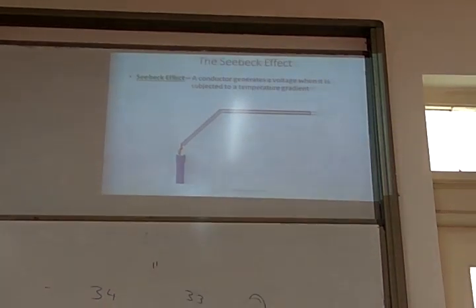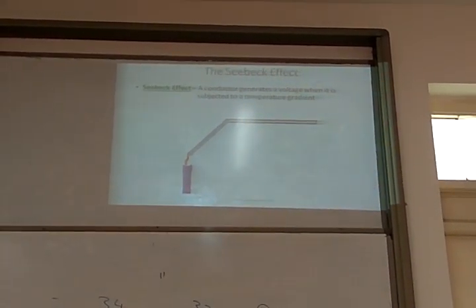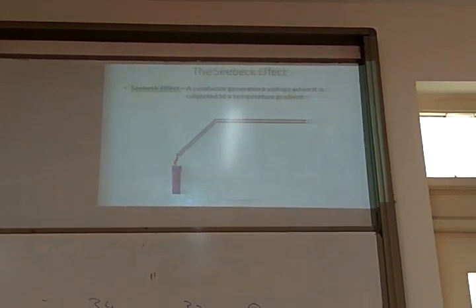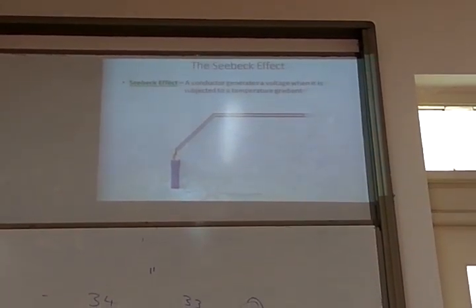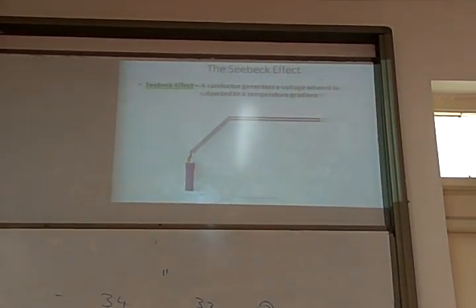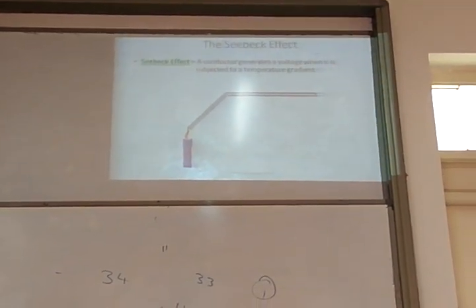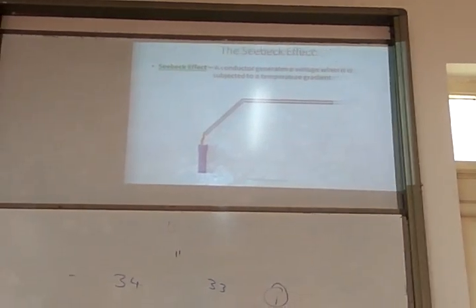Thermistors and RTD, resistance temperature device, both work on the resistance principle. One has a negative temperature coefficient, that is the thermistor. RTD has a positive temperature coefficient.